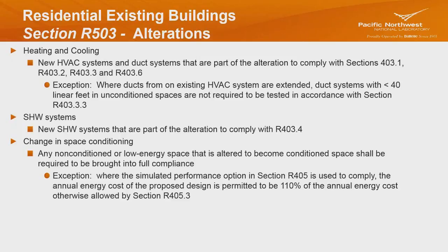And now let's get into change in space conditioning. There's change in space conditioning, and then there's change in occupancy. Two separate ones. So change in space conditioning means if you have any non-conditioned or low energy space that is to be altered and become conditioned space, it has to be brought up into full compliance. What does that mean? Let's say I have a garage, and I want to make it a family room. That's typical. That happens quite a bit. That's an unconditioned space that now I'm bringing up to conditioned space. So that would be considered an alteration.